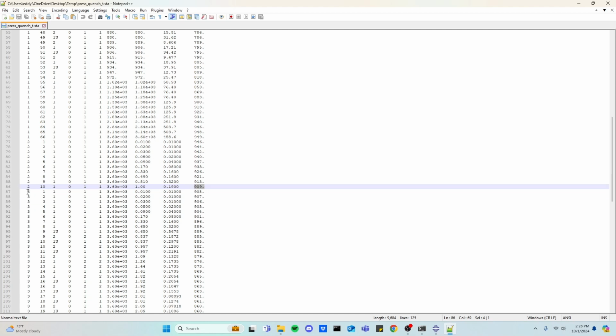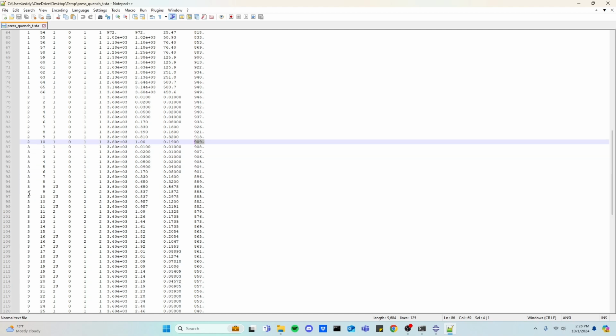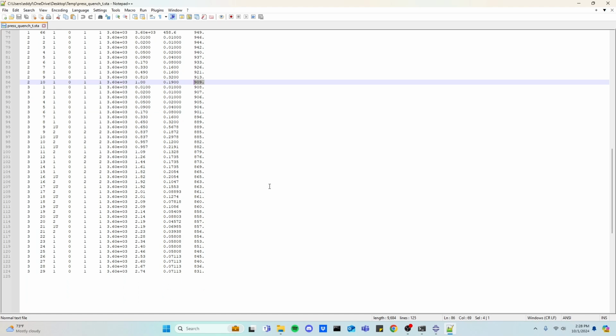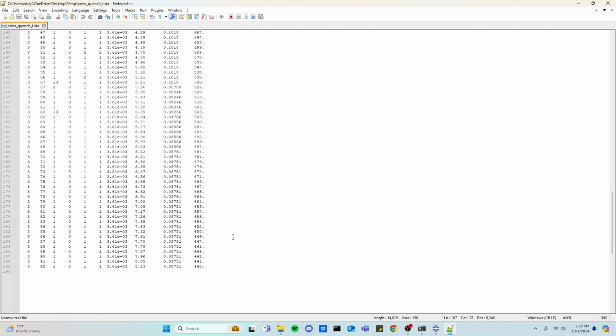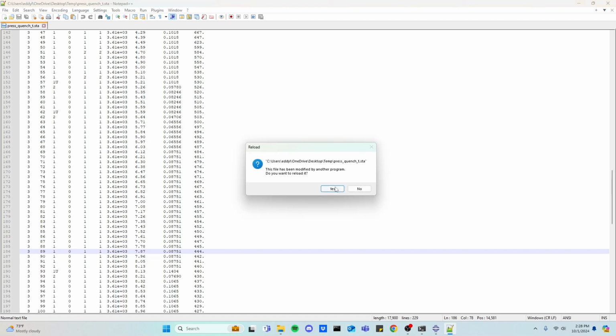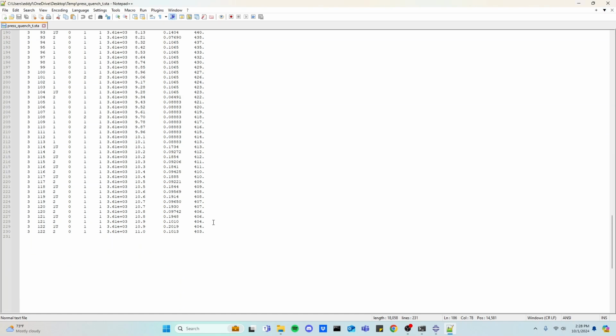And inside step 3 here is our actual oil quench. So our temperature starts to drop drastically, and the oil quench step, or when you have a quench step inside a Dante model, this step usually takes the longest just because of the high temperature gradient. So the 50 degrees versus the 950 degrees surface temperature of our part due to the heating step. So if we give this maybe a minute to run, this should be done in maybe 30 seconds to a minute.